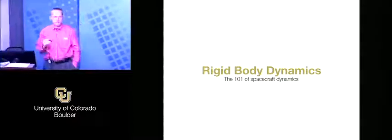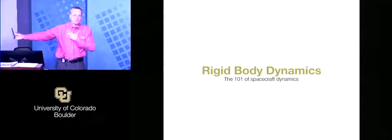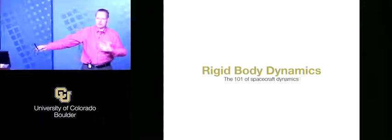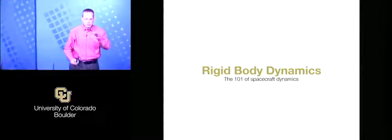Why is R dot not 0 if the body's frozen? Why isn't this location of this mass relative to my center of mass, that's the center of mass here, why is this derivative not 0? It's always at the same location, Billy. It is in the body frame, but not necessarily in the inertial frame. Exactly. That's the key.